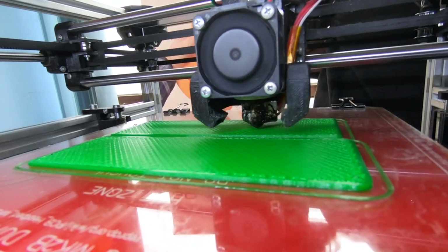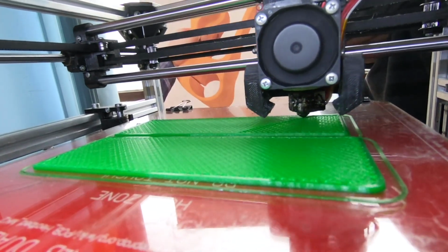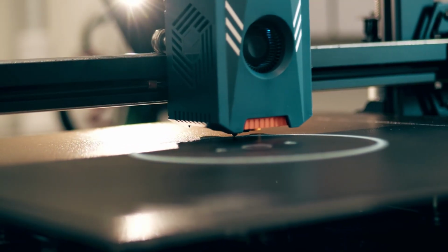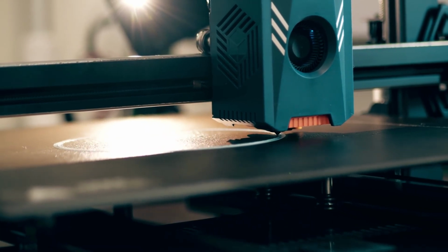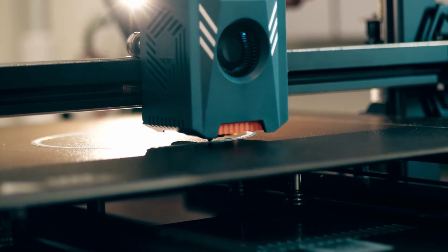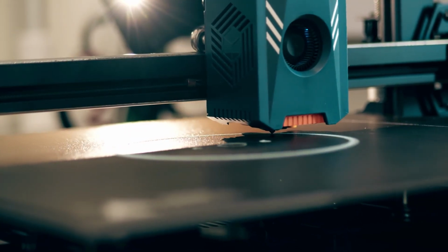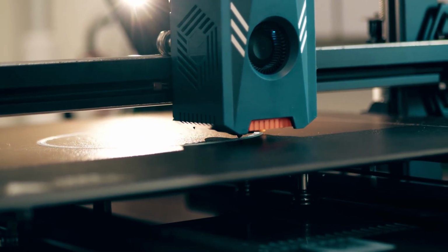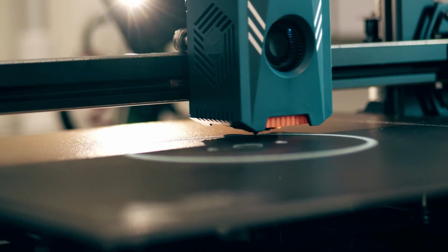Once walls and infill are planned, the slicer has to deal with one of the hardest problems in FDM printing: top and bottom surfaces. Bottom layers are printed directly on the bed. The slicer slows down, increases extrusion width, and often increases flow to help the plastic bond to the build surface. This is why first layer settings matter so much. The slicer is intentionally over-extruding slightly to compensate for microscopic gaps and surface imperfections.